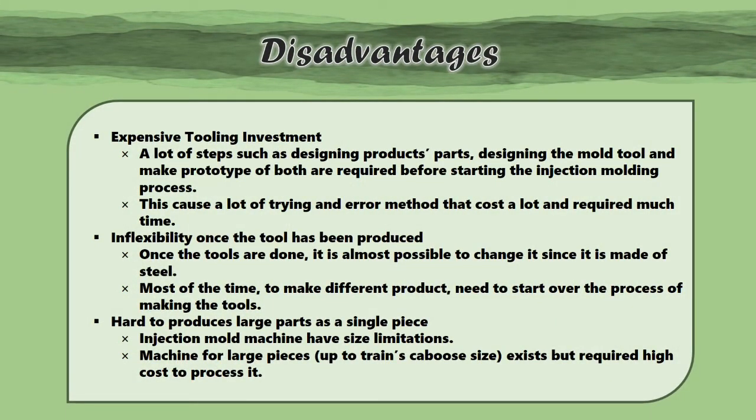However, there are some disadvantages of using this machine too. Apart from its expensive tooling investment, it is quite inflexible once the tool has been produced. This is because it is made of steel, so most of the time, if the product design is changed, we need to remake all the tooling for it.